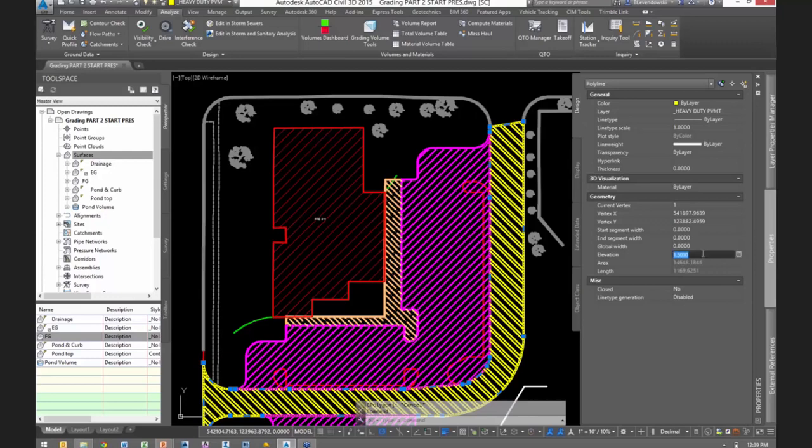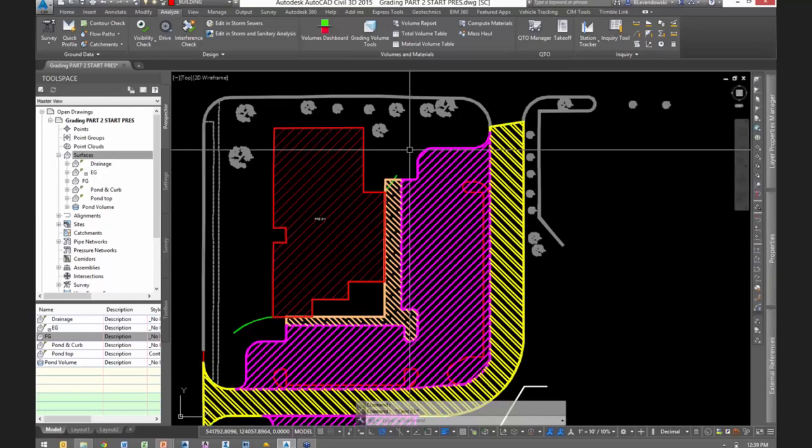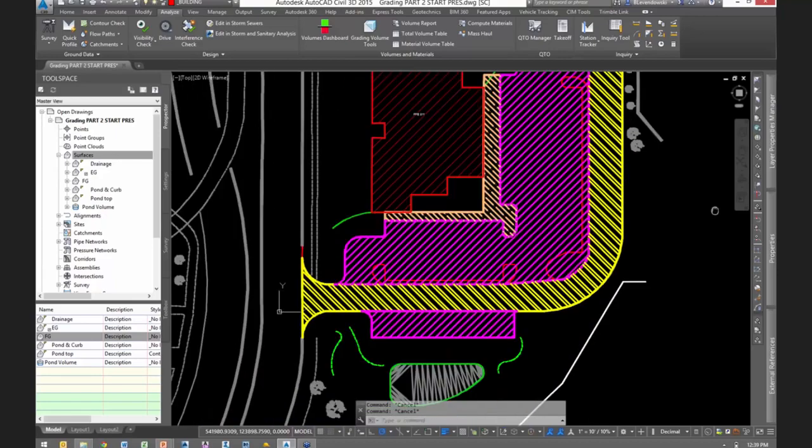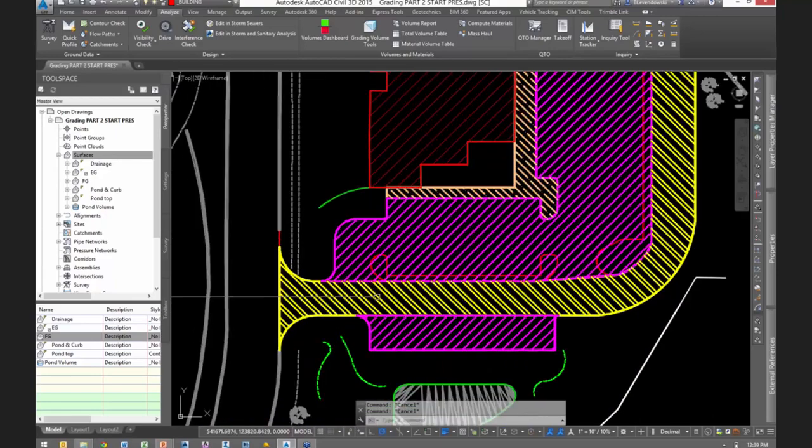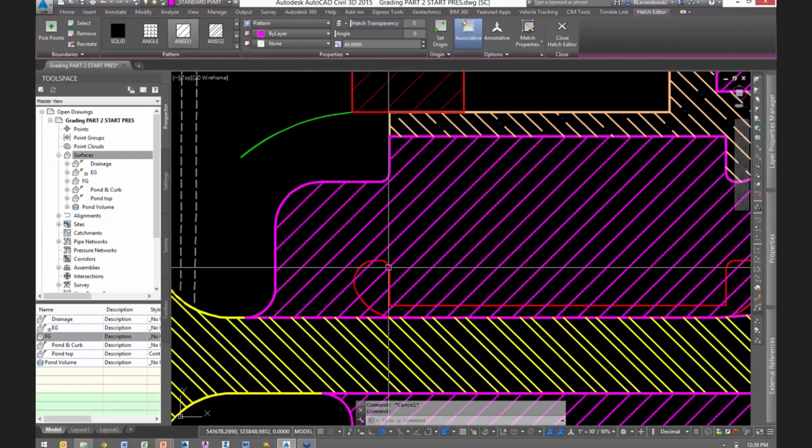So the way this works is we're going to first build a surface with polylines in it whose elevations are set to the depth of the subgrade itself. Okay, and we're going to make a number of surfaces to do this. So I'm going to keep going through it. It'll make sense as we get it together here. So it's quite a workflow, but it'll make sense once we have it completed.